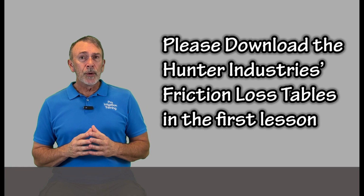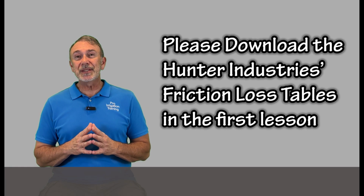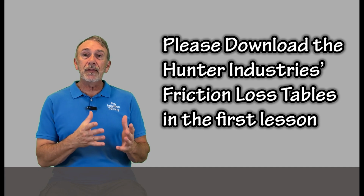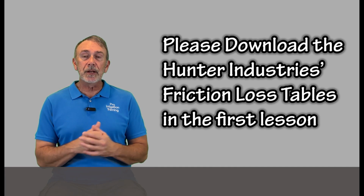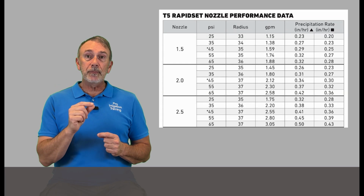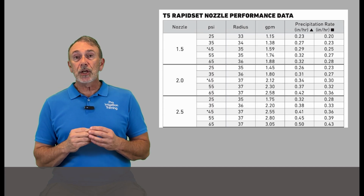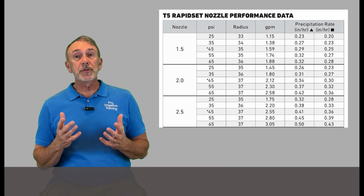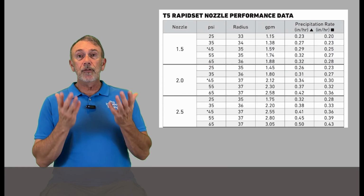So we always suggest that you design your systems at 80% of what the maximum is for that size of meter and that size of tubing that connects the meter to the main water line. Now also, as we design our systems, how we control the flow is by the number of heads that we put on a zone and the size of the nozzle that we put in the head, right? And so as you get different pressures, you're going to get a different amount of water that comes through there. As pressure goes up, flow goes up.